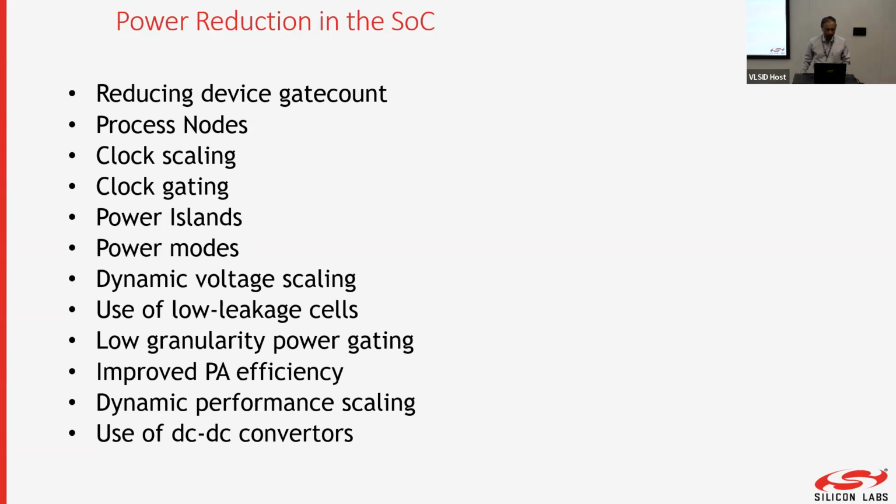It's not so easy. Then you have power islands. If a particular part of the circuit is not used at the moment, why bother even powering it? Forget about not clocking it. Can I even turn off the power? So you create power islands. Then you have power modes. You can have my SoC work in an intermediate power mode.